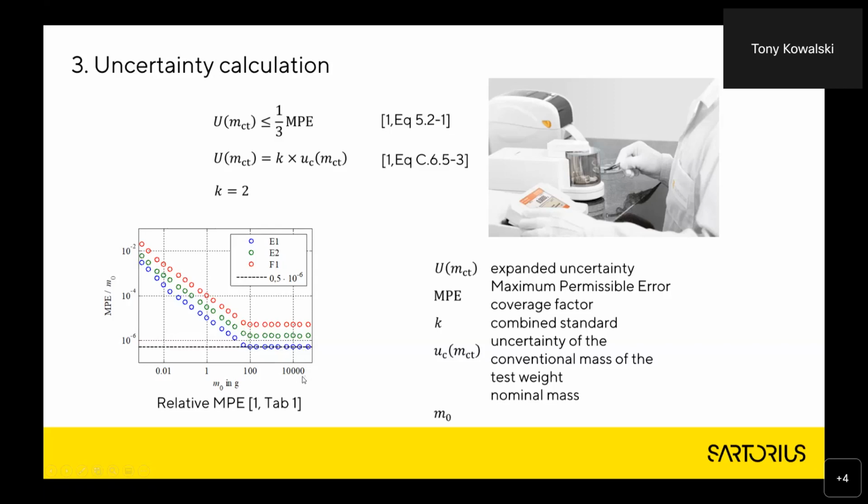By doing the uncertainty calculation, the repeatability calculation, we can be sure that the contribution from this particular comparator is no more than 1/3. So probably in this range, it's good to calibrate most of the weights down to 100 grams. But once we get below 100 grams, then its repeatability is not good enough to keep the uncertainty contribution below 1/3.